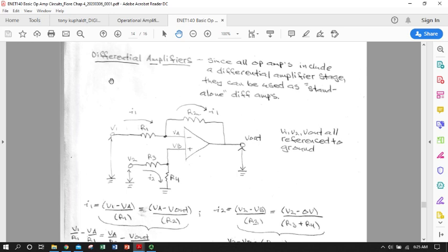You'll also notice when we're manipulating op-amps, there's always two input signals. Even if one is grounded, when we're using the other, we have effectively a voltage difference or a current difference going into both terminals. And that's because the first thing that you hit inside this hypothetical triangle of circuitry is usually a differential amplifier circuit. So we're going to take advantage of the fact that all op-amps are effectively diff amps, and we're going to look at putting in a little bit more complicated signal into both the inverting and non-inverting terminals and see what we get.